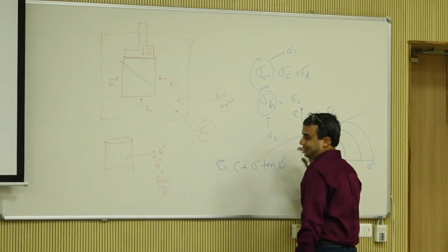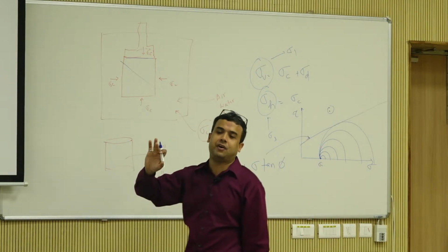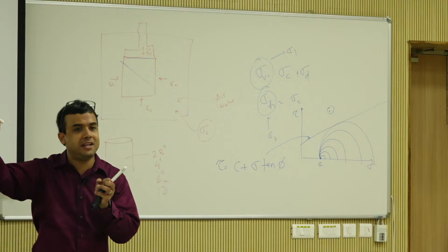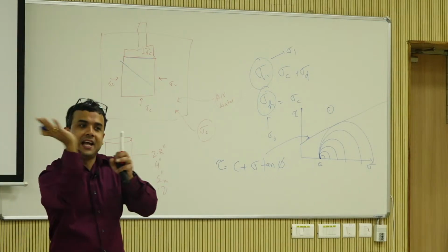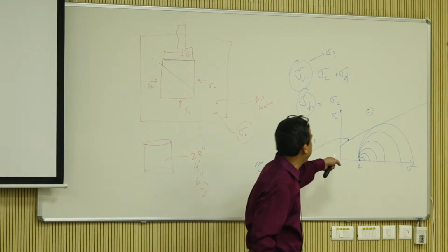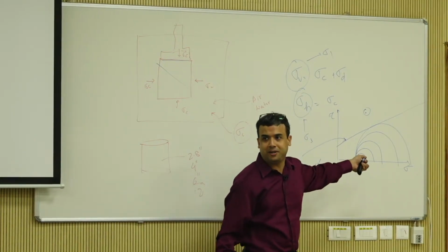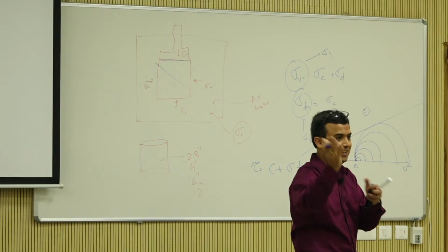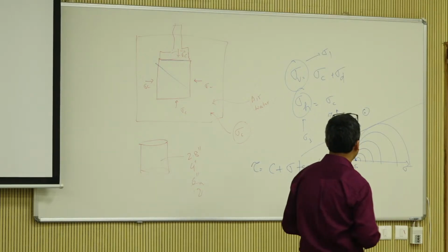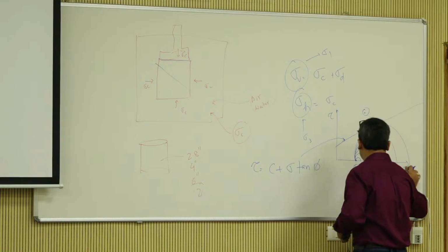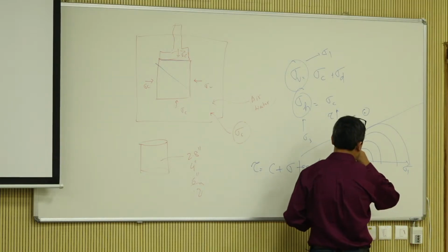A little bit of additional information for you. The Mohr Coulomb envelope is actually non-linear in nature, but you are doing a linear interpretation, and that is the reason a lot of times you have an interpreted C. So you just have to remember that it's not truly linear, it's a non-linear envelope. Okay. Now this is sigma 3, this is sigma 1, the major and minor principal stresses.